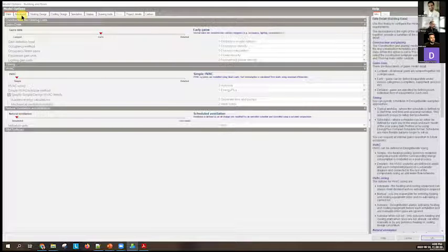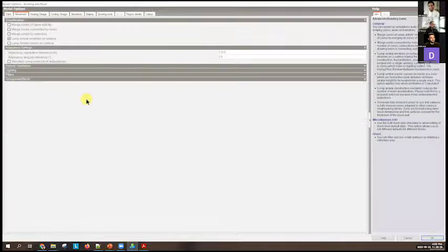Okay, so if I go to this advanced tab, I'm going to remove this lump similar window surface. And that was built when computers were expensive and memory was expensive. So the idea is that you can put one window on the wall, and if you've got exactly identical windows along that wall, you just model one and multiply by the number of windows. And that's no longer required. And of course, many buildings don't have that, so it's always better to get rid of that straight away.